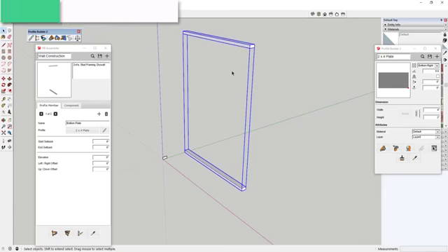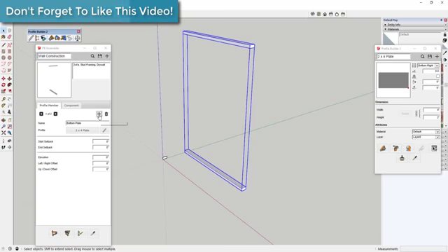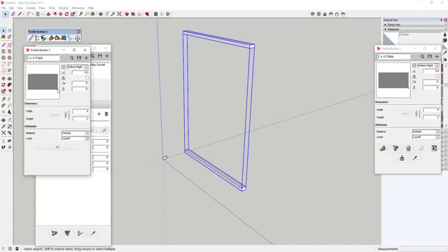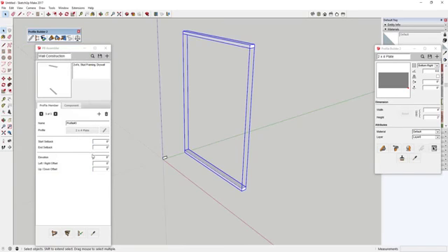Sometimes these walls are going to have more like a double top plate, so we'll go ahead and add one more. You can do the same thing, select this object, and probably give this one an elevation of 8 foot 6. Now when you refresh this, you can see it shows two 2x4s on here.